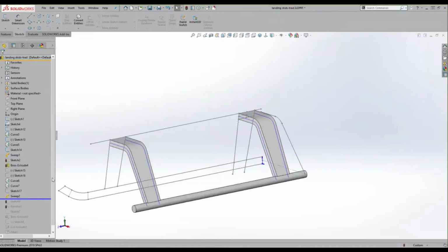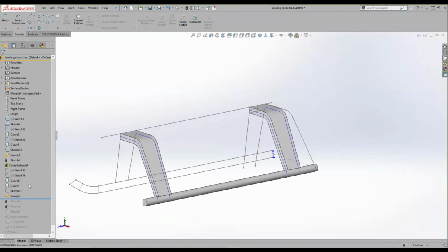This is that situation where we evaluate it, and then we build the second extruded boss, or excuse me, extruded boss is the little pipe right there, and the same sketches, projected curves, profile, sweep with guide curves, and then complete the model. Kind of a silly example, but again, just something else to think about.